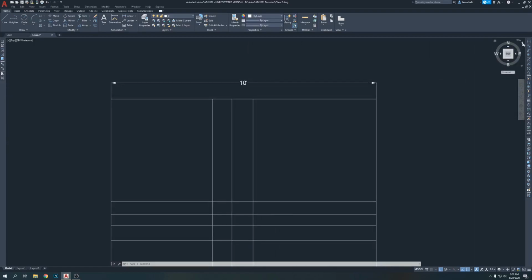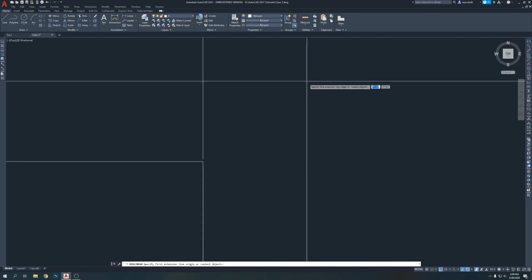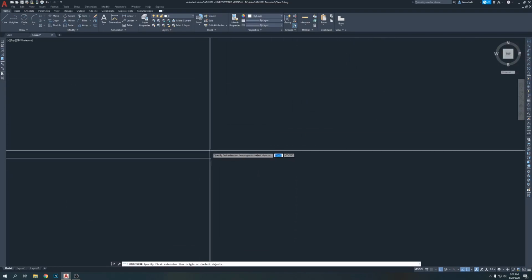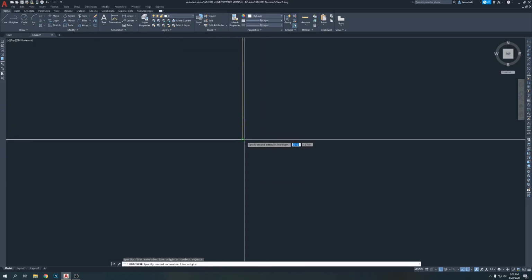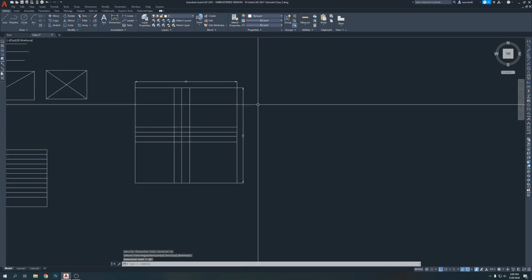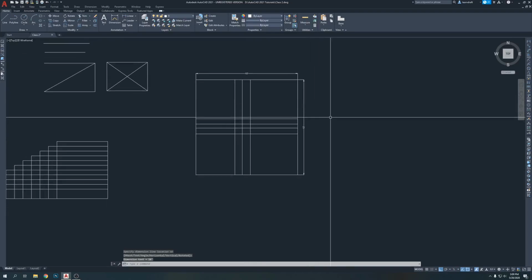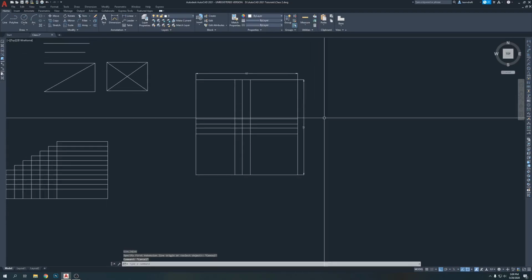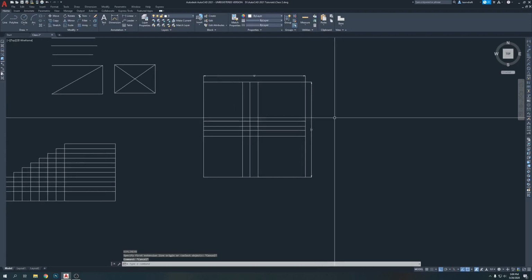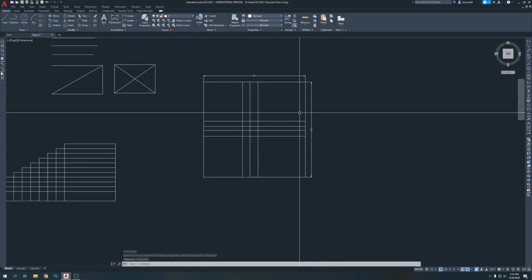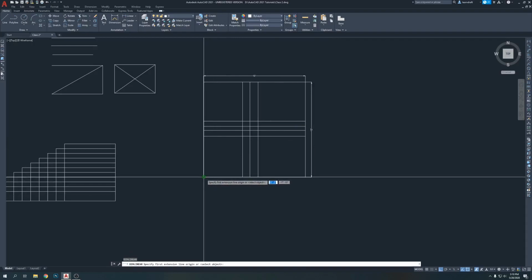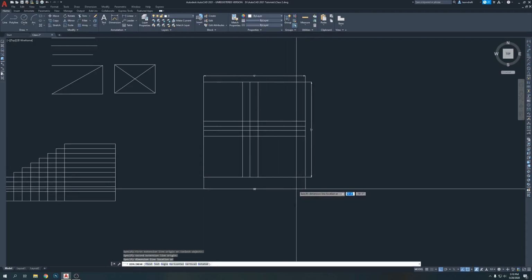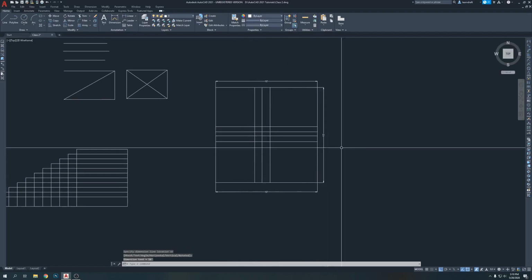Now we're gonna click here, and then I'm gonna go there, select this point. You do not select here, you select here, and then you select here, and then you click here. Now you can press enter to repeat the command, but you did not learn yet the command for dimension, which is DLI. DLI. Enter. Click, click, and click. So how are we going to do that?